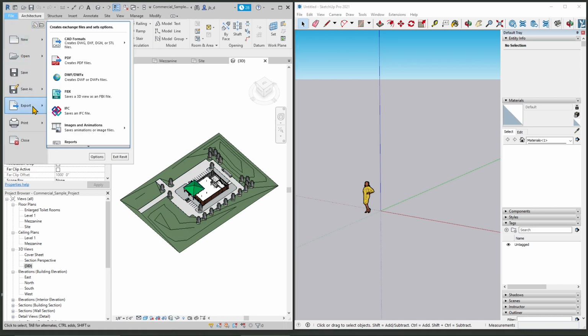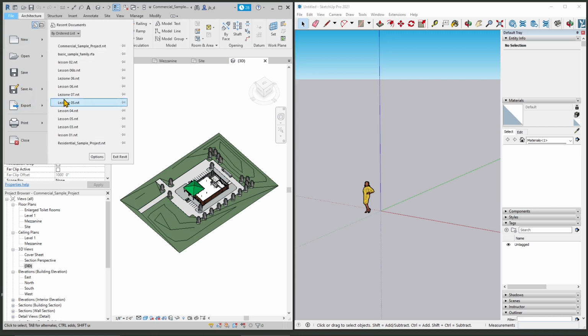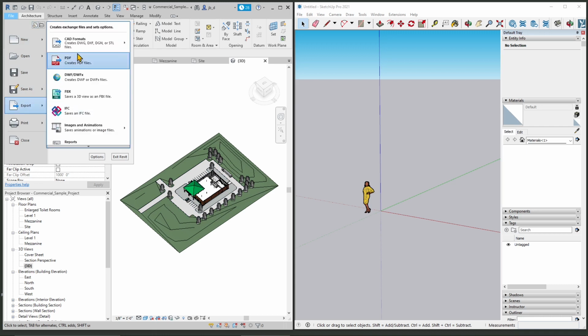So if we go to the export file, export, we can choose here different CAD formats. You also have STL, which is for 3D printing, but well, the DXF will be fine. You can also use DWG, but it's practically the same. Now, if it doesn't work with DXF, you can try with others, but usually this is the best and more compatible with all the other CAD software.